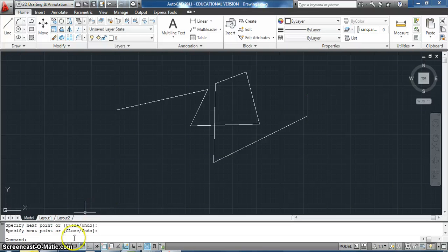If we get on the bottom here and have a look at some of our toolboxes down the bottom, we have the constraints, the snap mode, the grid display, ortho, some polar tracking, an important one, object snap, 3D object snap. We have some other object snap tracking devices and some other allowance and disallowance of dynamics and dynamic input.